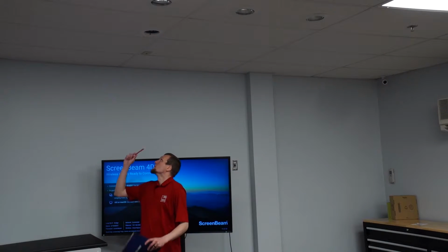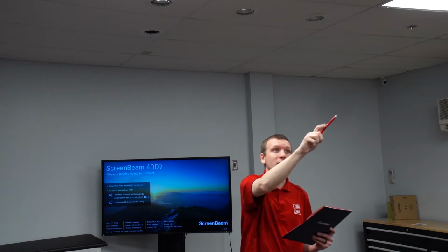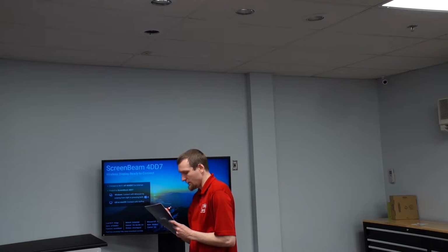Next, we need to know where we can actually mount the projection device on the actual ceiling. For drop ceiling, that actually becomes a little bit easier because each one of the tiles has a set distance, 2 feet in our case, of their width. So you can actually count out the number of tiles in the ceiling, 1, 2, 3, 4, and know that you can go, hey, 0 to 6, I can mount my projector. I can't do it for the next 2 tiles, but I can do it for the following tiles, so that's 14 to 16. And you'll be able to quickly jot down the actual distances you can mount your projector at. That's going to be important when we start talking about throw ratios and actually selecting our projector.